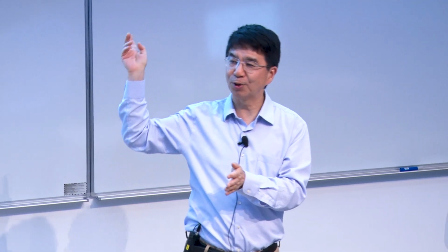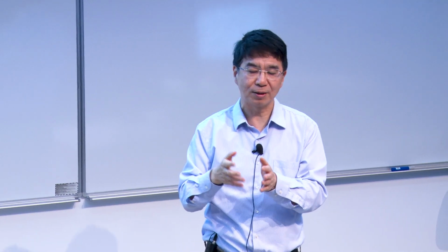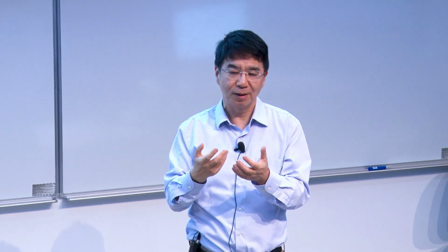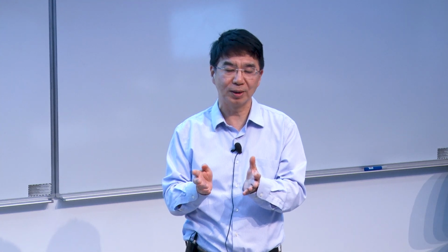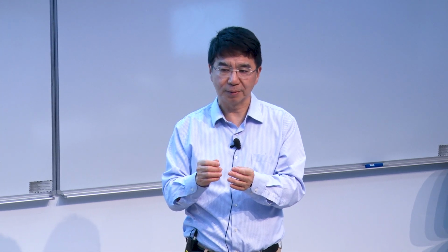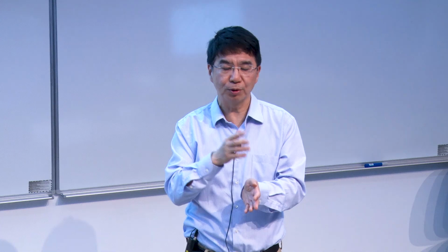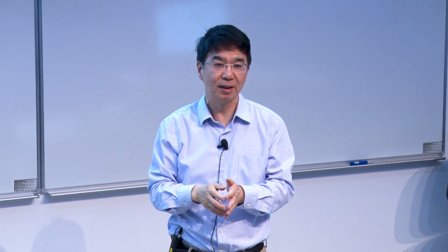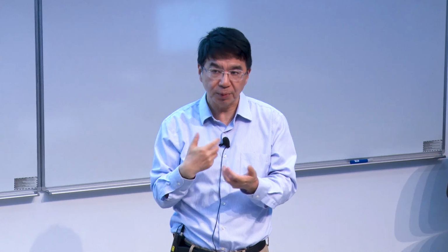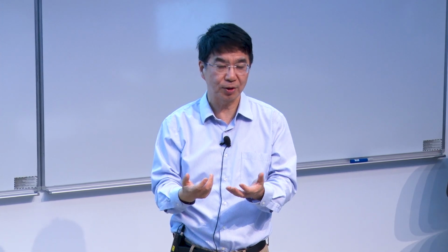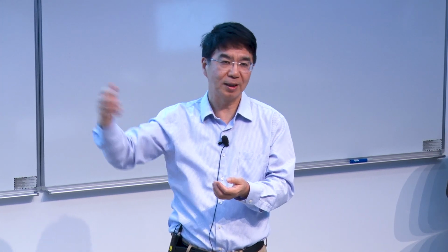So very early on, I showed you these 2001, 2003 papers when we started high-level synthesis, so that's our goal. We said we can be better than human designs because we can introduce all these extra registers, and then in fact we can get a higher frequency design. So that's why the motive is to consider this multi-cycle communication. In high-level synthesis, because we generate the finite state machines and the circuit, we have control over how many stages you can go.